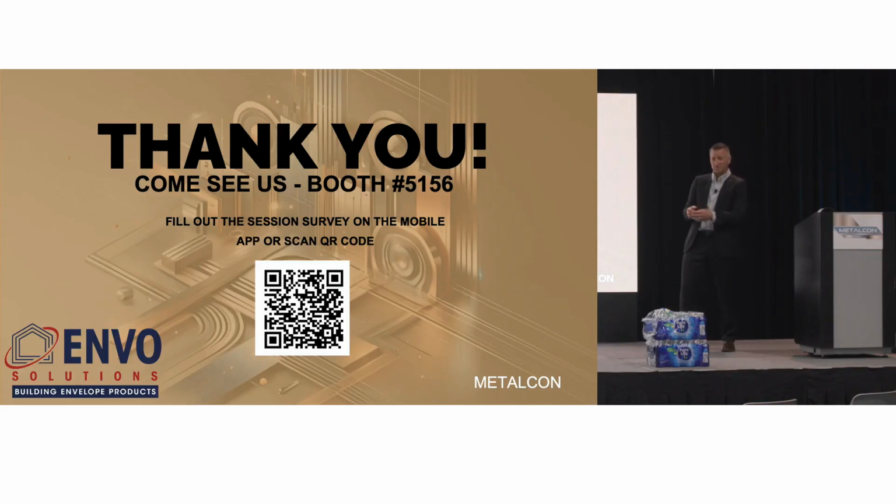The green dowel boards, the things that you put in your insulation, your plain old styrofoams, they burn, they smoke, they turn to flaming jelly. They are not allowed to be exposed in a building. If you've got metal on the outside, you've got drywall on the inside, you can bury that type of foam in a cavity, but you cannot leave it exposed. There are only 2 manufacturers that have the fire rating to be left exposed. So be careful of that when you start to think about rigid board. All rigid board is not equal.